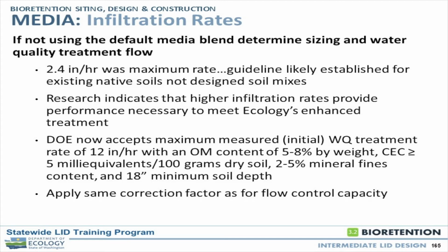As we've talked about, the research indicates that higher infiltration rates provide the performance necessary to meet this enhanced treatment when you're using 18 inches of this stuff. As we talked about, Ecology now accepts 12 inches per hour for the high end. So 1 inch per hour minimum, 12 inches per hour maximum. Those are the infiltration rates that you use when you're designing your own media.